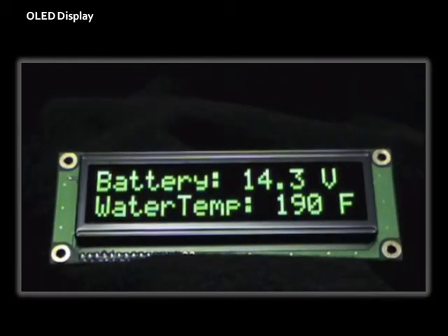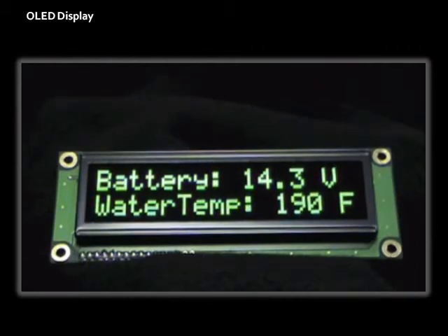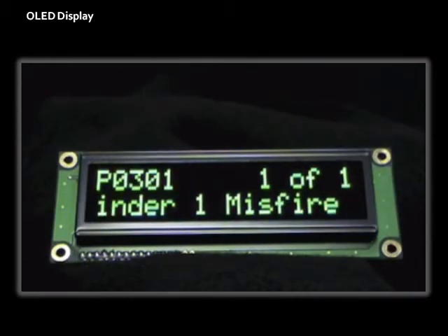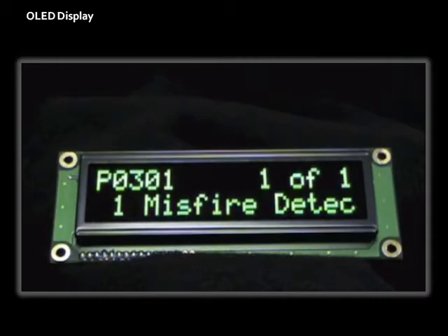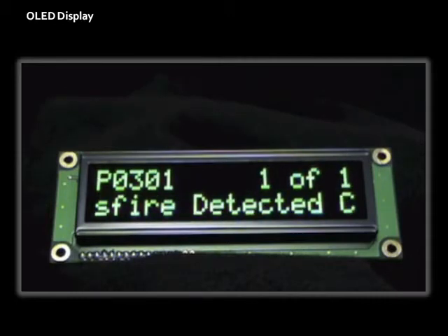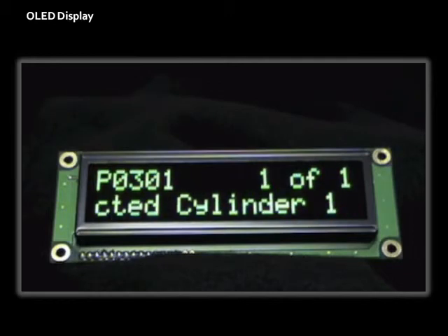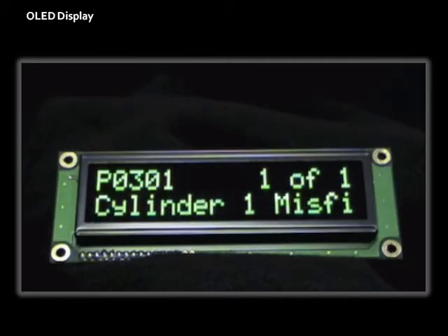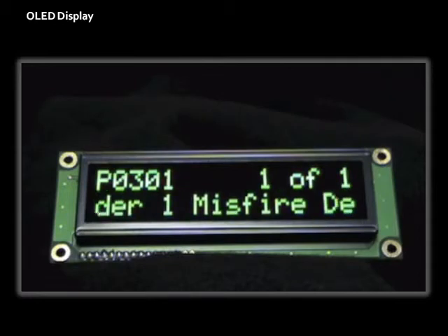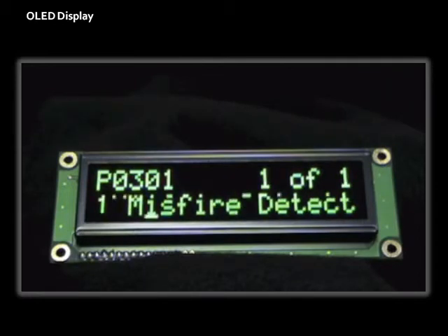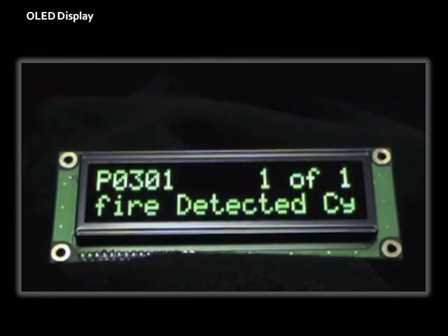These displays require a built-in controller to provide the timing and voltage levels for the OLED. OLED displays can come in many different formats, including dot matrix character up to 4 rows by 20 characters with built-in language fonts, full monochrome graphic type up to 320 by 240 pixels, and up to full color graphic type featuring red, green, and blue subpixels similar to a TFT.